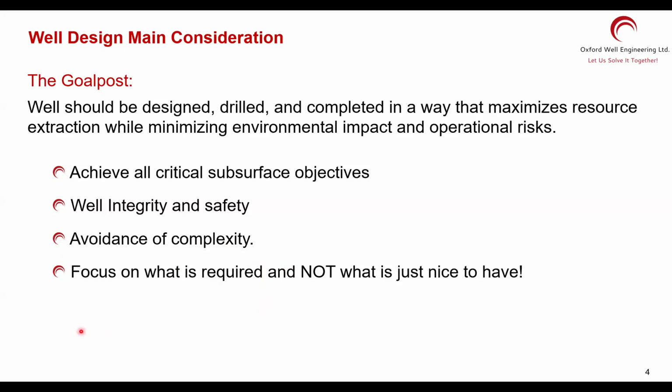The well design is your tool for finding the truth. A lot of the time you are just finding the truth. You are seeing issues with hole cleaning, for example, cuttings are not getting to surface. You want to find the truth. If you call any experienced drilling engineer, he will tell you, oh, actually, this is the RPM. We have very low RPM. Let's increase the RPM and the flow. That's the wrong way to approach it. Yes, of course, you can try it if you want to be asleep. Then you can just follow these guidelines which somebody gave to you. How about doing a modeling of the status quo, replicating this in the well design and finding out what the current parameters should be.